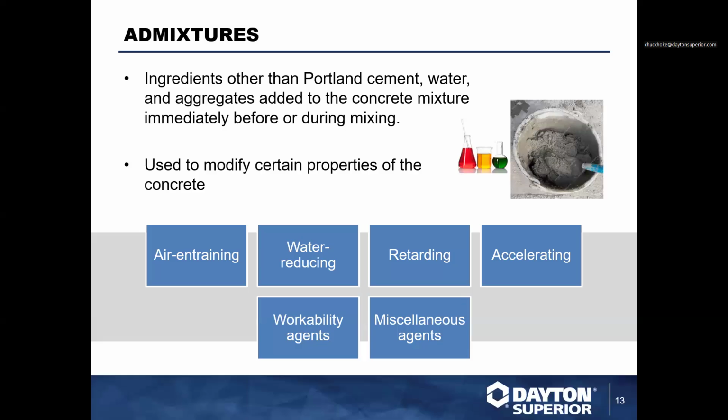Workability agents and miscellaneous agents, which I like to call foo-foo dust. They can make everything happen from chemical resistance to high early strength to freeze-thaw resistance, etc. So those are all different component pieces that can be added to a concrete mix to actually enhance the workability and the performance of the concrete mix.